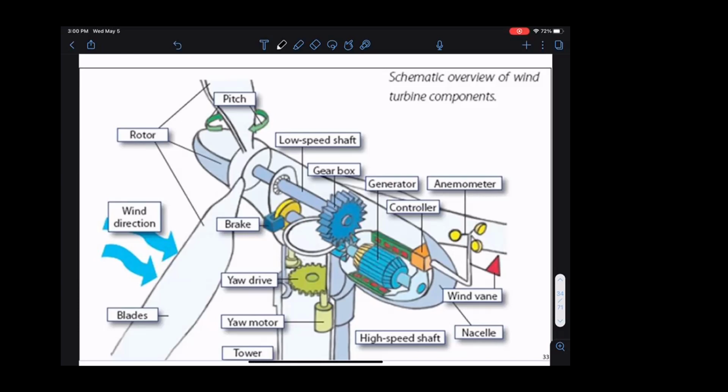What we want is the load equals the power, because of conservation of energy, extra power has to go somewhere. We don't have a cheap way of storing extra power yet. So from an operator's perspective, if I know what my load is, I want my generator to produce the amount of energy that's required by my load, not extra. If it's extra, I don't know what to do with it.